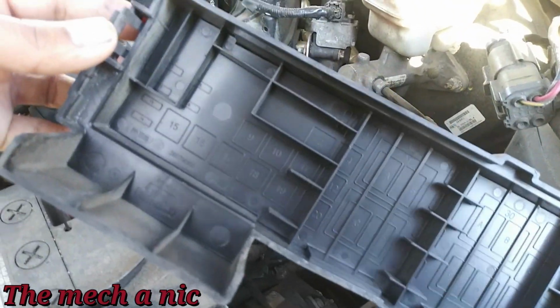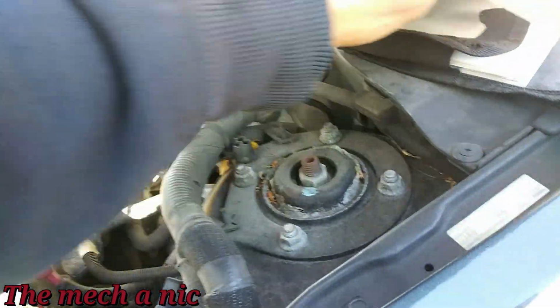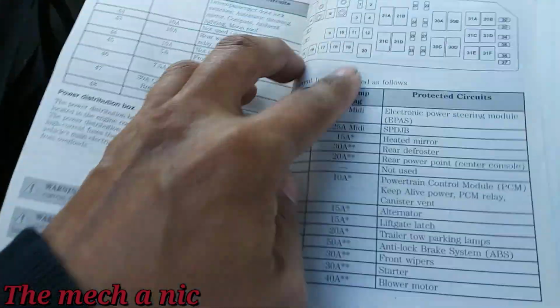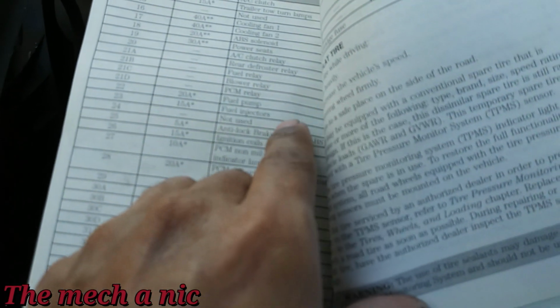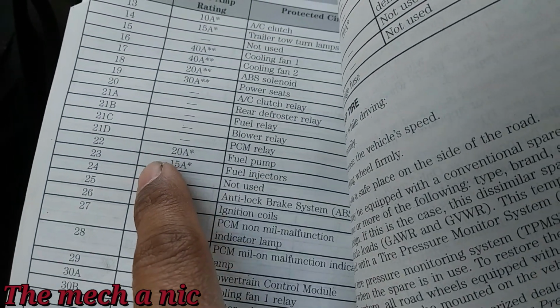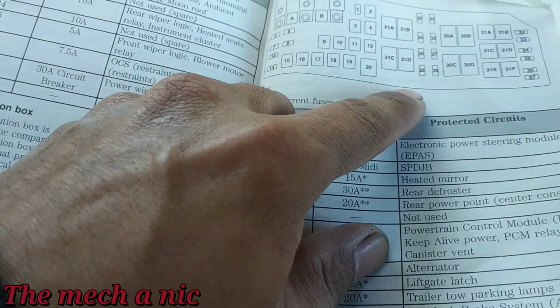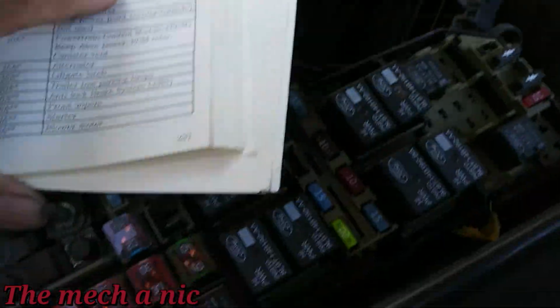And since Ford does not label any of their fuse boxes, I had to pull out the owner's manual. And what I'm looking for is the fuel injector fuse. So let's see. We're on this page. See right there, fuel injectors number 23. It should be a 15 amp. So if we come back over here, 23 right there. So that's going to correspond.